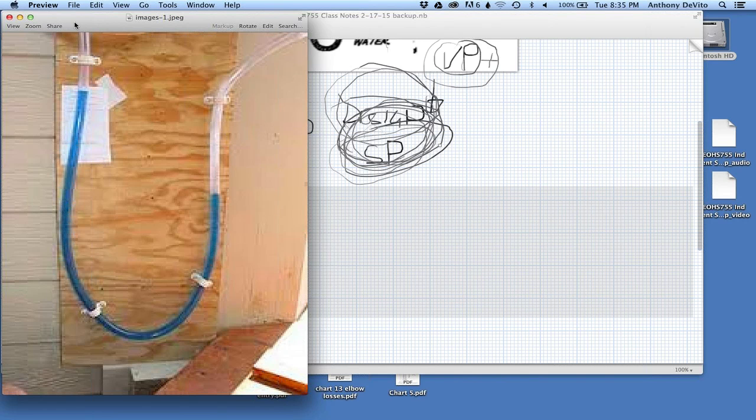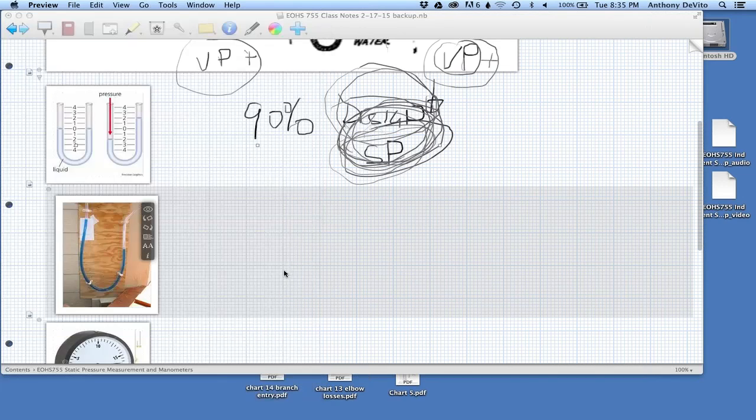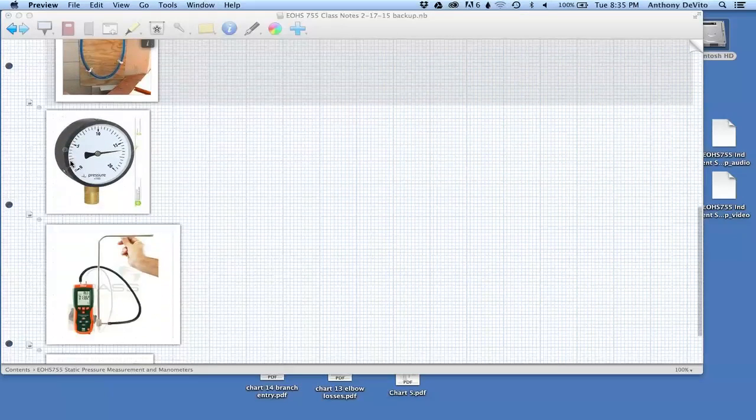Okay, so we're measuring the difference between the two. Just to give you an idea, industrially, if you looked at an air conditioning system, you'd see a simple gauge. This just uses a spring, so it pushes against the spring, and the spring either reads in PSI, pounds per square inch, or in HVAC systems, it may actually read in inches of water.